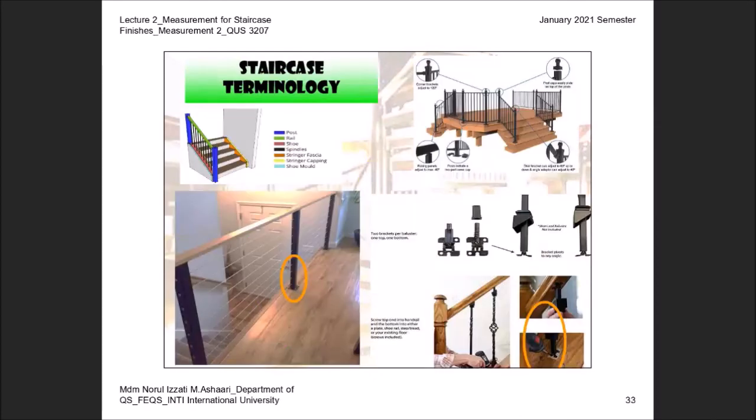And then I also would like to highlight here the term isolated baluster. You will see the word isolated baluster where the baluster is different from others, and then the way they install is normally directly on the floor here, either on the floor or directly in the concrete staircase, where the material is made maybe from timber or maybe from steel. You need to have the base plate. This is known as plate, P-L-A-T-E.